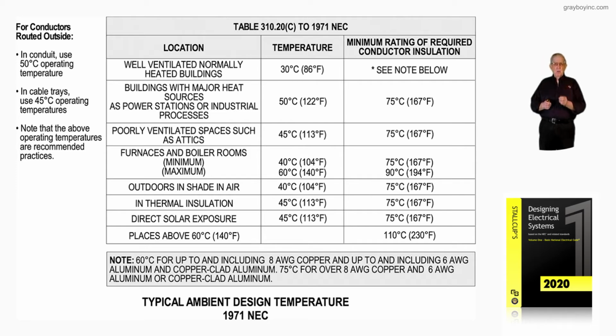But people took this to heart. We had folks wanting in a dwelling unit where it wasn't properly vented and the circuits were very seldom ever used. They were running number 6 wire and then splicing with number 12 and dropping it down in the wall to terminate to lighting fixtures and plugs.